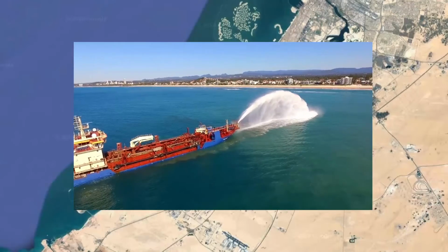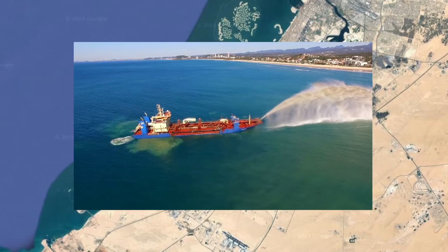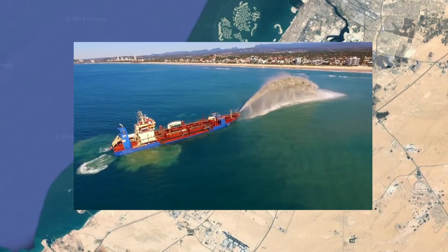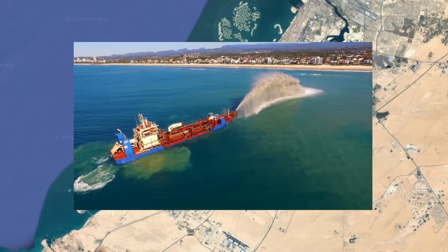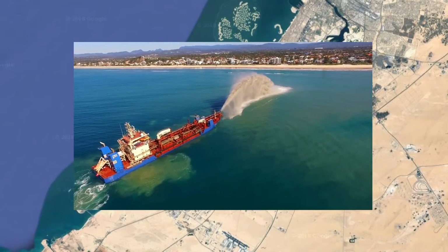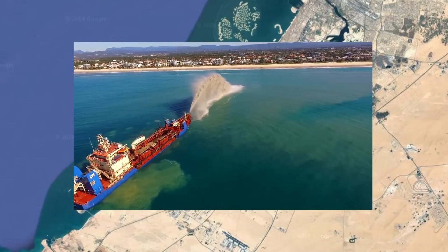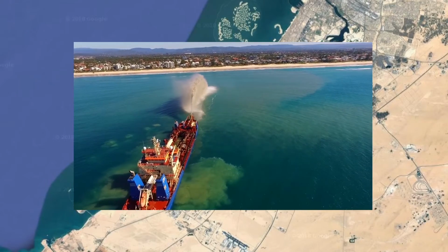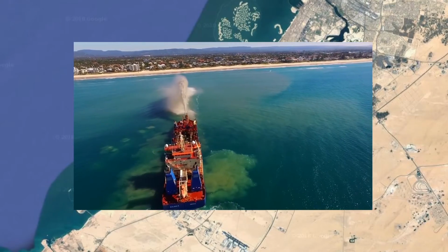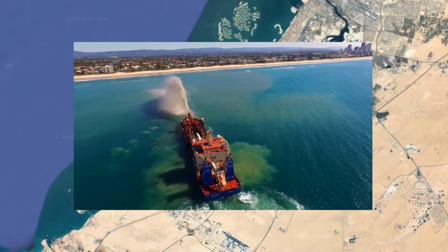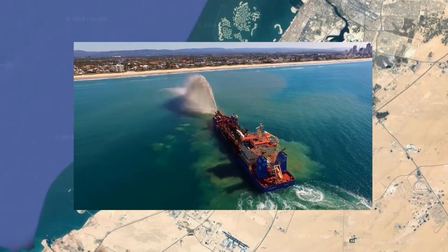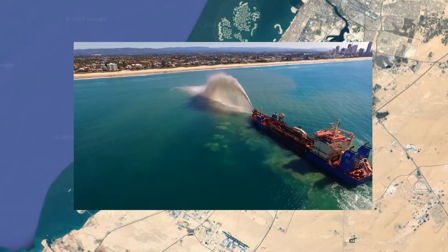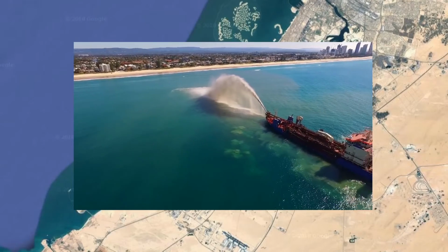A simple way to create new land utilises a ship that can pump seabed material and precisely direct it to a target site. A typical ship is able to pump 30,000 tonnes of material per hour from its spray tube, which has a typical diameter of about 1 metre. For efficient and safe operation, continuous measurement of the density distribution of the mud and water slurry is critical. Too much water will cause the material to diffuse away from the target site. Too much mud will cause pump overloads and reduce projection range control.